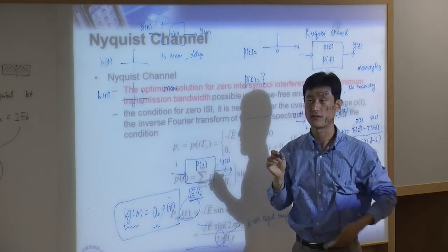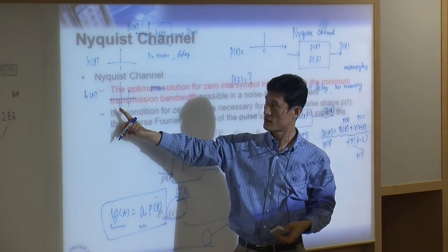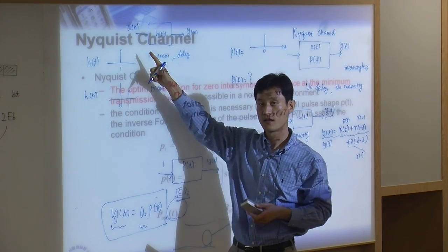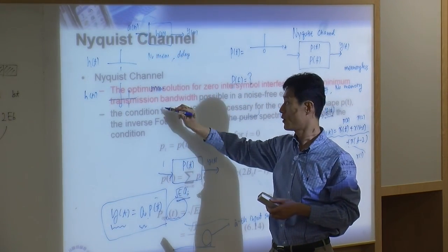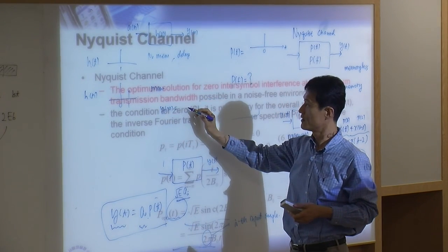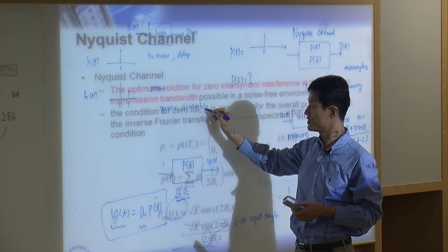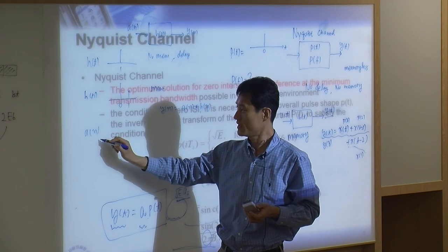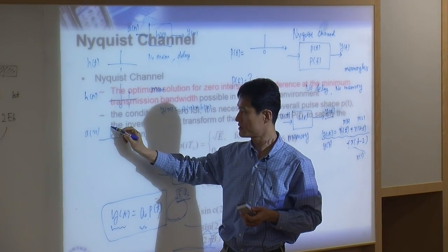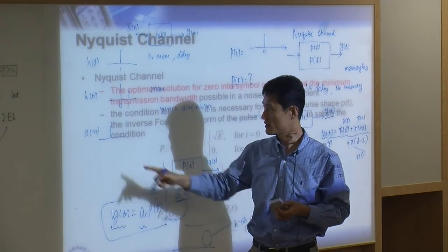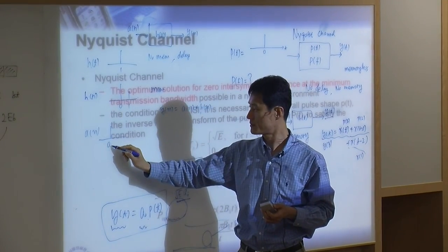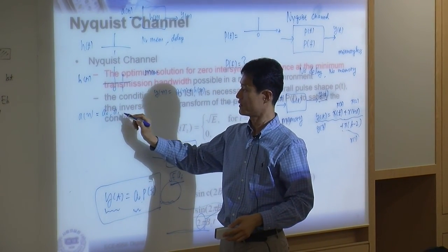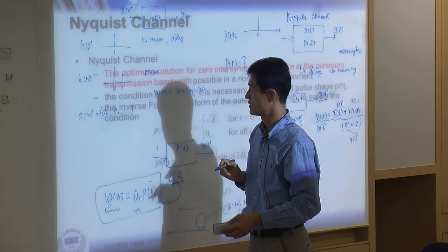Let's make everything discrete. If you have this impulse response, and you get the input a[n], then what is going to be y[n]? The output y[n] is, of course, a[n] convolved with h[n], right? So let's say we have any input a[n]. There are so many taps, but just think about only two. This is the input. Let's call this a0, a1.